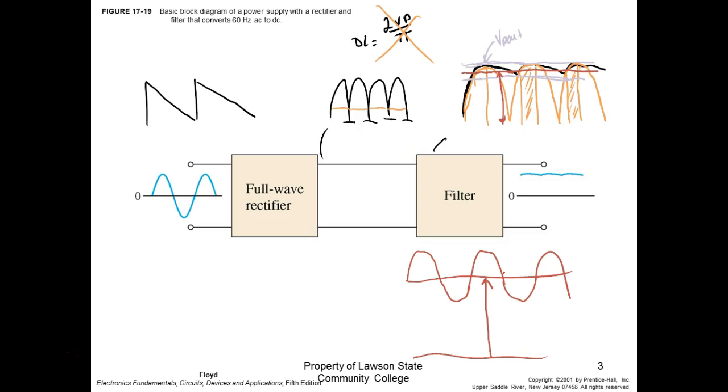That makes sense? And later on, when we get into amplifiers, most of our amplifiers don't amplify AC, they amplify DC. So what do we make them look like they amplify AC? We superimpose the AC on a DC level. And that's the way transistor amplifiers work.